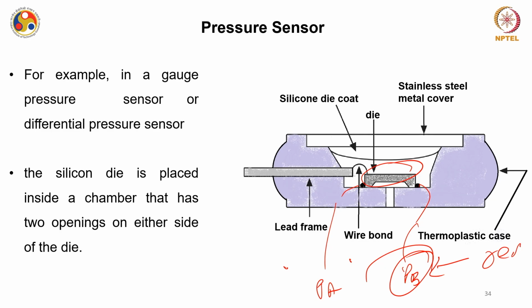We have seen one example where, by back etching silicon, we have generated a cavity, and it can be used as a sealed ambient. It can be used as a reference vacuum. So, these are the different devices that are possible with the piezoresistive principle, with silicon of course, and this is the most popular pressure sensor that exists in the market based on these microelectronics techniques.